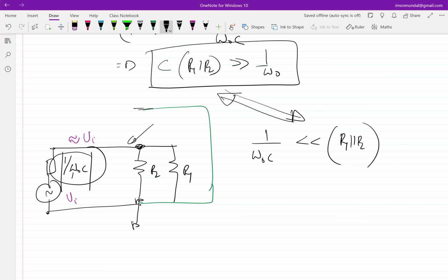So when I am choosing a value of the capacitor in this particular application, do you want the time constant to be very large or very small? Very large, right? Why? Yeah, voltage across the capacitor should be 2 volt all the time, right? So essentially what we are saying is that the voltage across the capacitor should not change at all, isn't it?